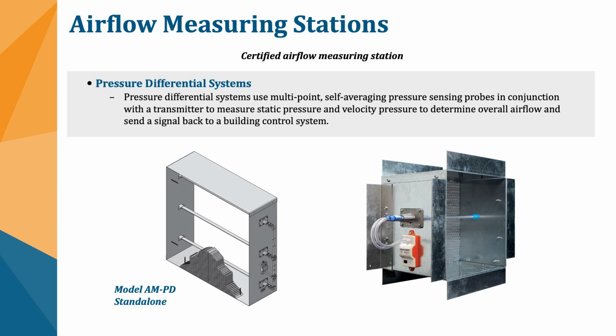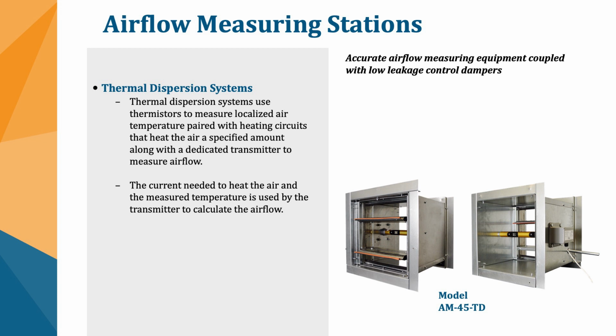If you don't have enough CFM, you can either open up a damper upstream or downstream of that fan to create more volume, or you can throttle the fans as well. There's a couple of different ways the building measurement system can adjust that. And it's typically going to be you're going to throttle the fans and adjust the damper at the same time to get that CFM, and typically open it up and increase that velocity to get more CFM or reduce it if you have enough CFM.